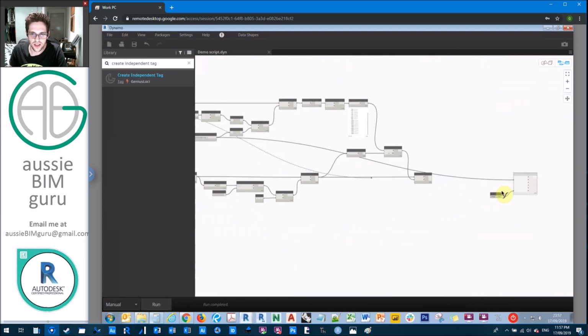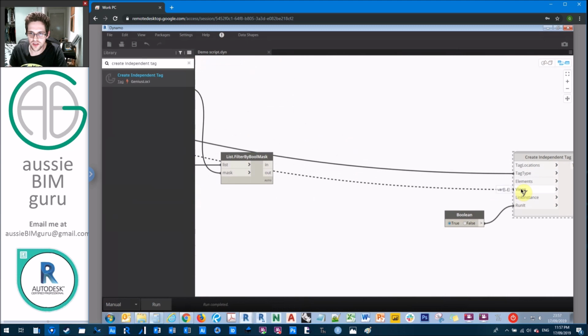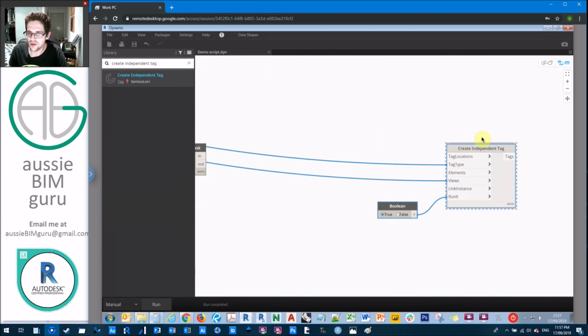You could also just create another active view node, but I prefer to only generate data once wherever possible, unless you're really complicating your script by pulling on elements from way back in the script. I think 2 is probably okay. I wouldn't do it too many times just to avoid confusing users.